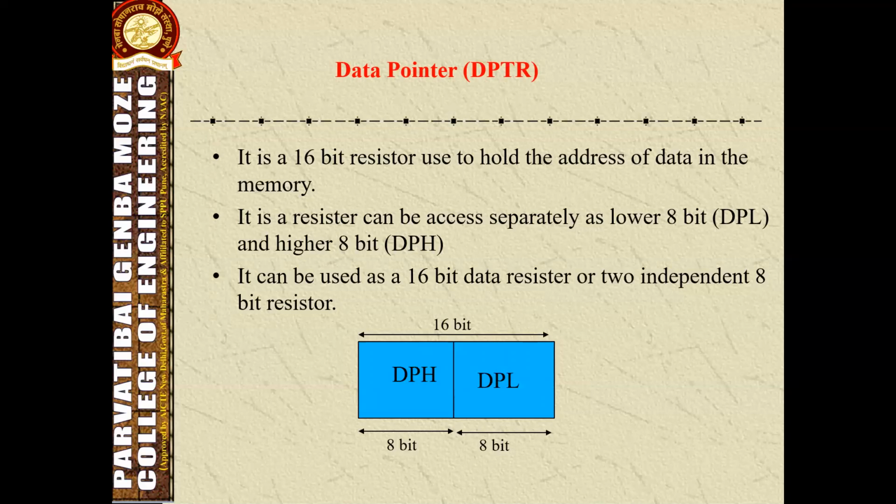Here, the data address will be held in this register, and it can be used as a 16-bit data register or as two independent 8-bit registers. The program counter was 8-bit, but this one is a 16-bit register.